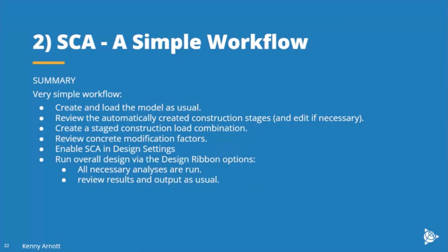Okay, so just to summarize things once again, we've created a very simple workflow. You create and load the model as you would have always done. Then you can review the automatically created construction stages. Create a stage construction load combination where you describe the load that will apply during the construction phases. Review those concrete modification factors. Enable stage construction analysis to be considered during the design of the members in the structure. And then run overall analysis and design again, as you always would have done. And then review your results and output again, as you would always have done.